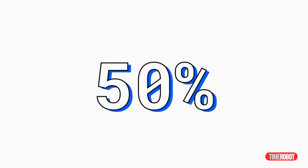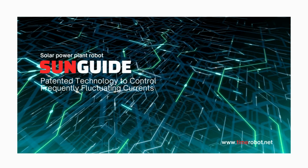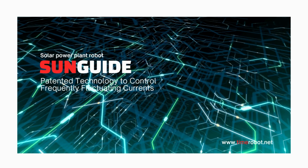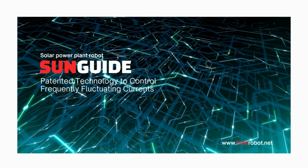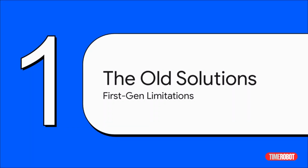Just one panel getting partially shaded can slash the output of that entire string by up to 50%. I mean, think about that. Half of your potential power just gone in an instant, all because of one little shadow. That's a massive amount of wasted energy and, of course, lost money. Now, of course, the industry has known about this problem for years, and they have come up with some solutions. But, as we're about to see, these first-generation fixes, well, they come with their own pretty serious set of limitations.